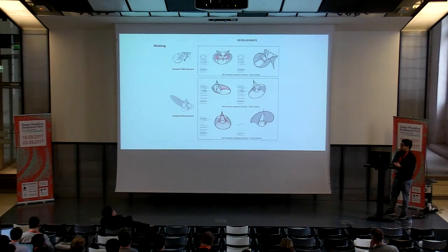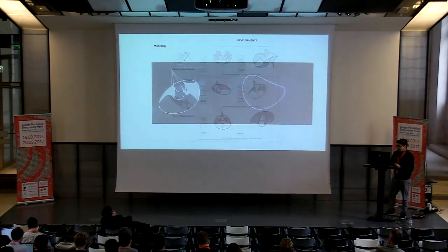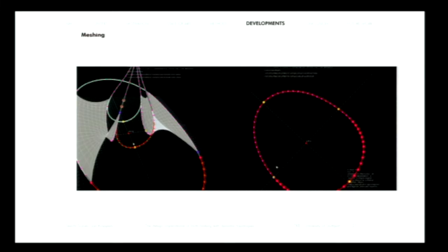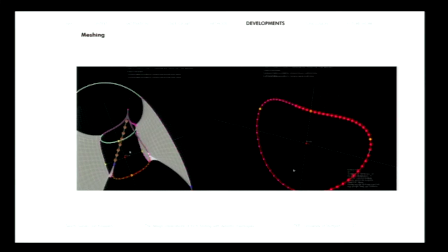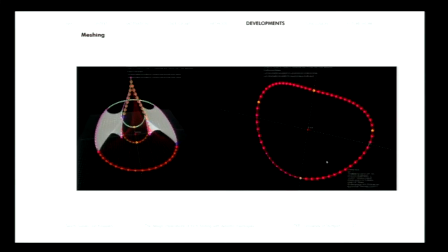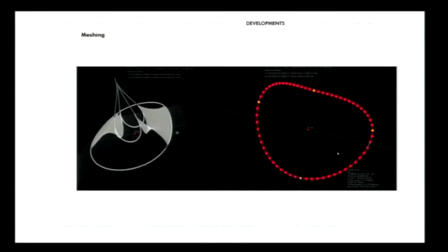For semi-constrained conditions, where about half of the nodes are fixed on the edge, we use a direct method for computing the local UV values and generating quad faces. For fully constrained conditions, where all the nodes are fixed on the polygonal boundary, we implement an advancing front method for paving rows of quads along this polygonal boundary.